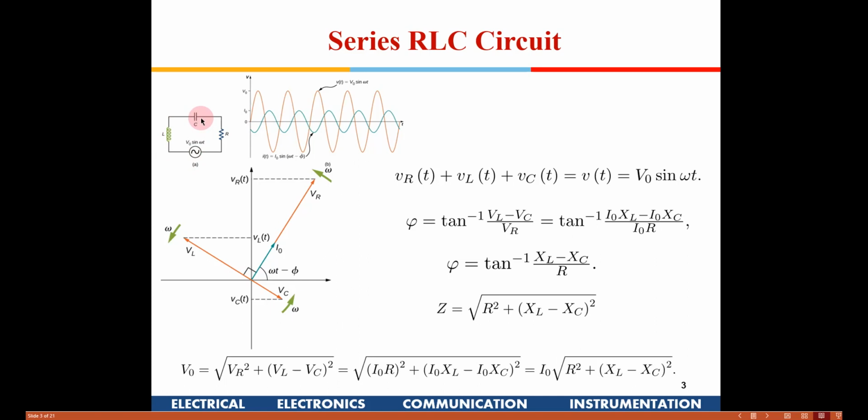So you have to take due precaution in your design. You have to be careful with your designs, because if you offer a low impedance with L and C, it can result in currents and voltages which are very high. The terminal voltages across these can be very high, and those high voltages can cause sparks.